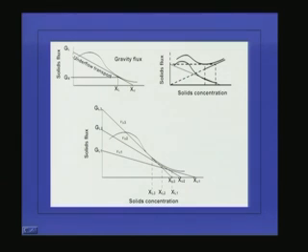Yoshida suggested an easy graphical solution method for this solid flux. What he has done is take the gravity flux alone, by considering the similar triangle theory. Your gravity flux comes like this, and the flux due to underflow comes like this, and if you take the sum of these two, you get the same thing. Here the triangle was like this and your gravity flux was like this. Take the same triangle on this side, and you get the underflow transport like this and the gravity flux like this.